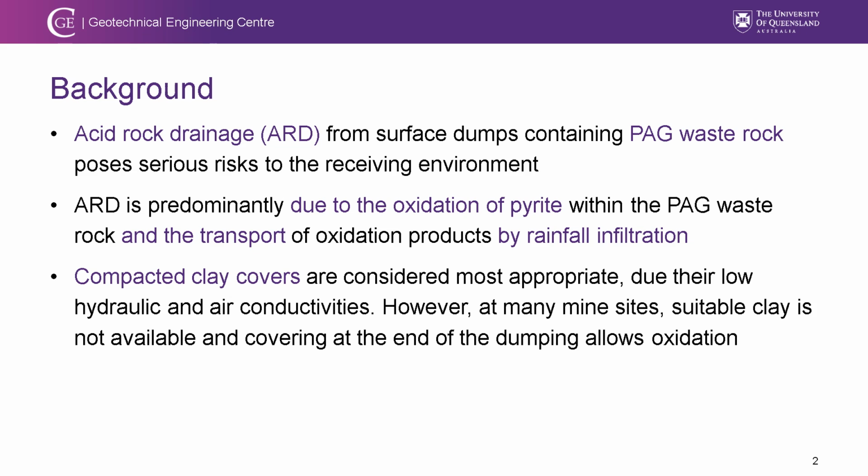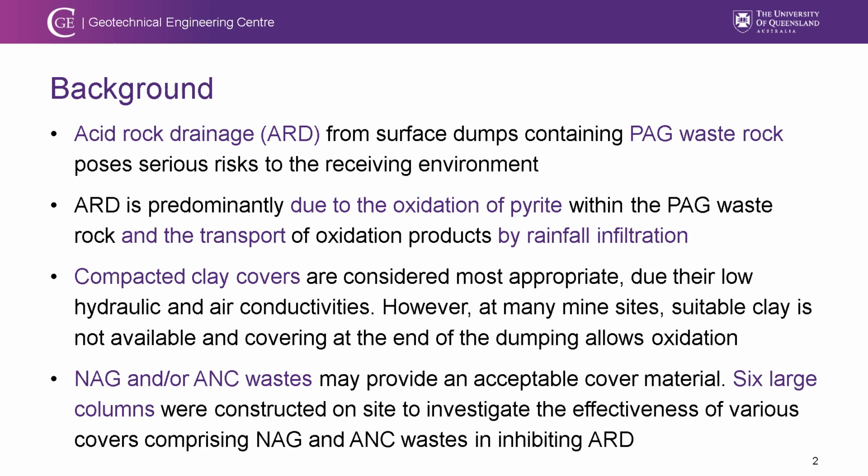But in many sites, clay is not available. And also covers are being done at the end of the dumping activity. During the activities, the oxidation cannot be minimized. However, it is very common that at the site, non-acid generating wastes and acid neutralization wastes are available. So it is possible that once co-disposal is done, it could potentially reduce the acidity of the leachate as well as minimize the acid rock drainage process.